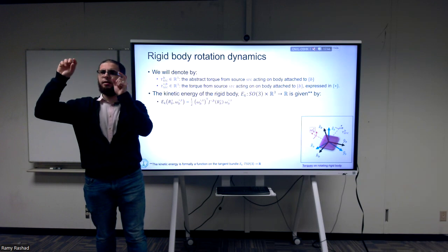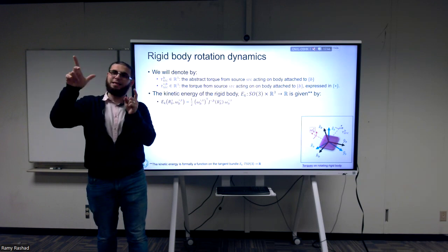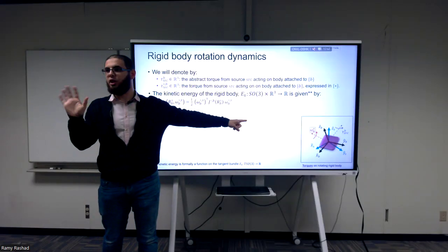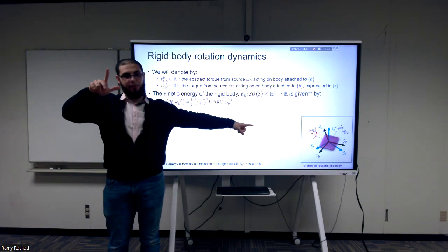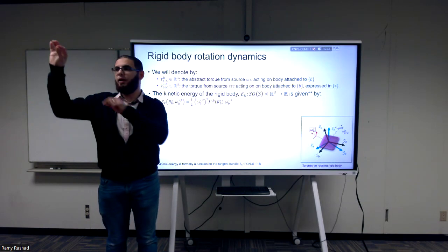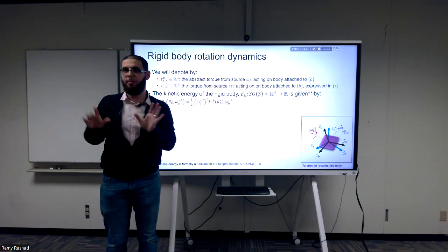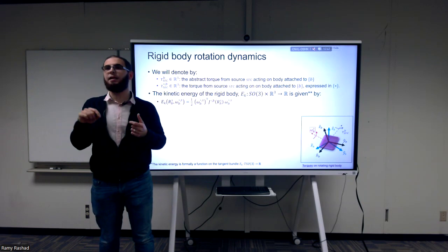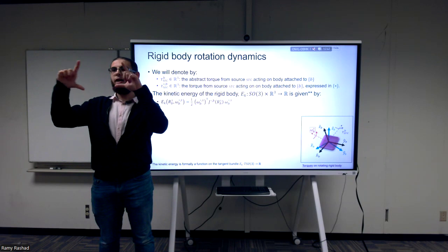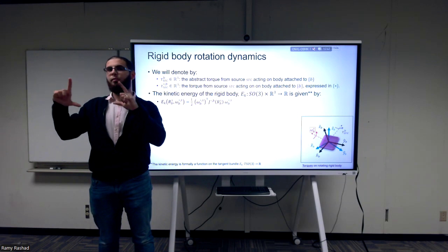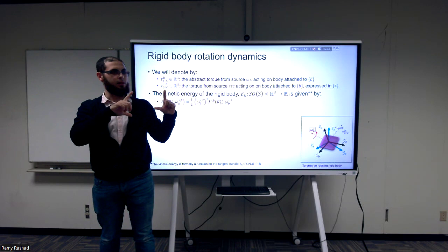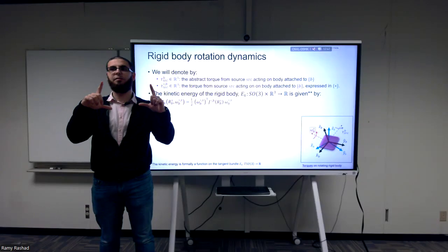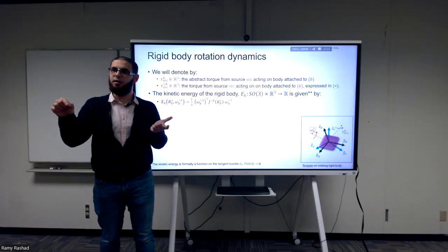Of course, you're saying, okay, the off diagonal should be 0. It's only if you choose a certain way of representing this body fixed frame. In general, not. So in general, the 6 numbers, if you put the frame which is attached to the body in a certain way, you can eliminate the off diagonal ones, which is off topic for now. We're gonna come back to that later. But what I want to make here is that even what you just said is not right. Because when you have a matrix, you need to tell me which frame you're talking about. When I represent the moment of inertia tensor in general as a matrix, you need to tell me if it is expressed in the frame B or in the frame S.